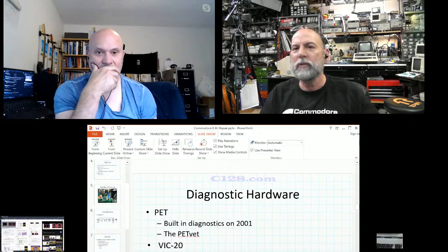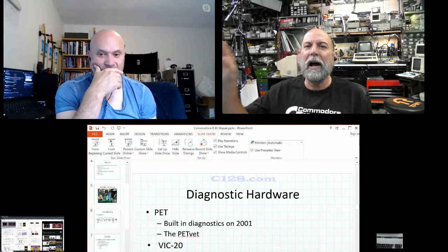It goes to ROM, and real soon after that, it'll do a stack call, or it'll jump to a location, and that means RAM has to work. So within about 20 cycles of a processor, almost everything has to work. Maybe not the I/O, the input-output devices, like reading the keyboard, for example. Everything can work, but you can't read the keyboard. Okay, that's getting down to that device that's broken. But the problem is you've got to have a lot working before nothing works at all.